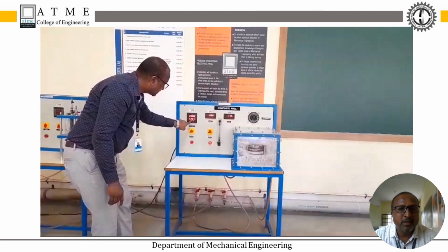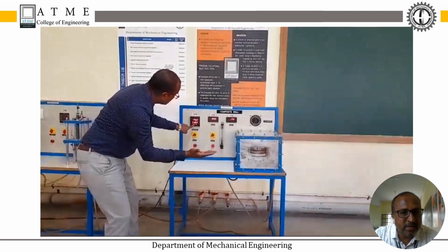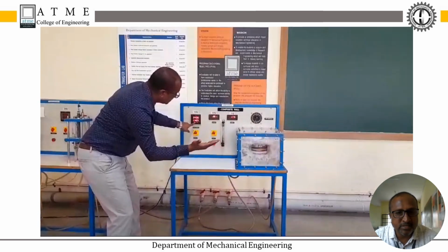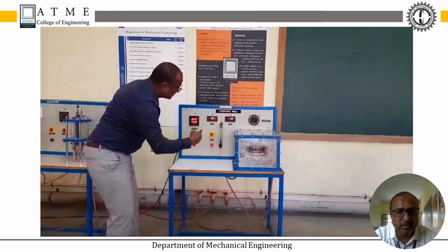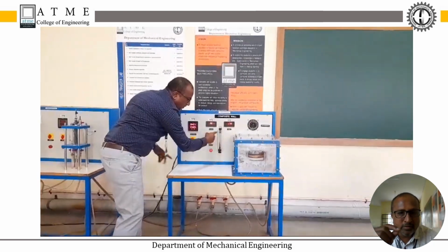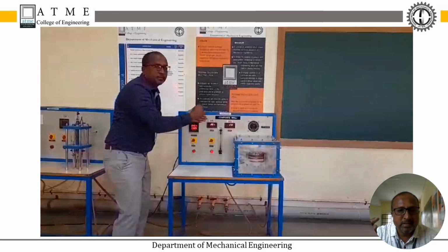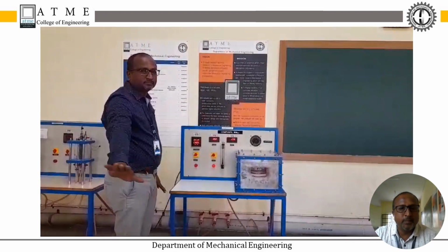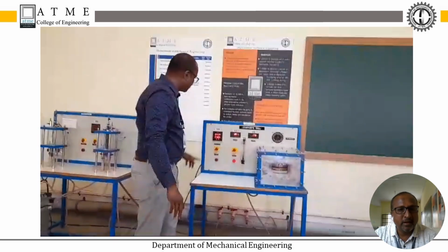At that point we note down the temperatures at this part, where the channels are selected for different junctions. Thermocouples are connected to different channels, and as I press the button there, I can note down the different temperature readings. At the same time, note the voltage, current, as well as the flow rate of water and the thermostat, and all those things are tabulated, and the calculation is done. Okay, this is what the experiment is all about.